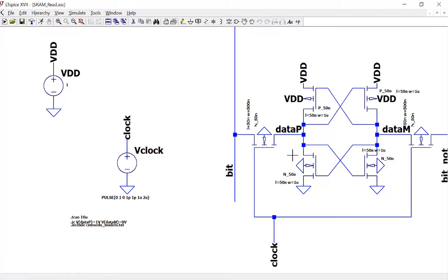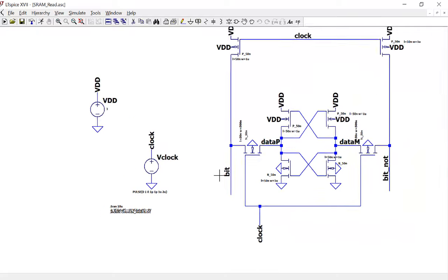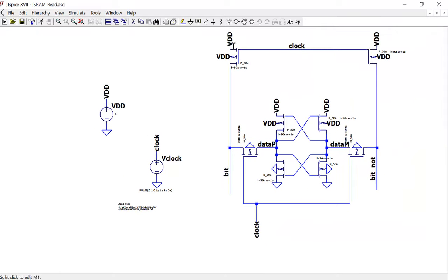It's like the initial value is stored in the memory cell. Because it's a reading, it's not writing, right? So you want to assume it's already been written. Have 2 states, right? 1, 0 and 0, 1. Just simulate both of the conditions, and see if you're reading the correct value of 2 bit here. It's very simple. Any questions so far? The circuit is just 2 PMOSes and the latch and 2 switches.